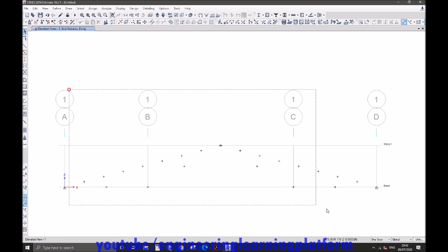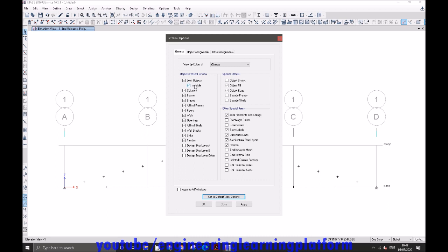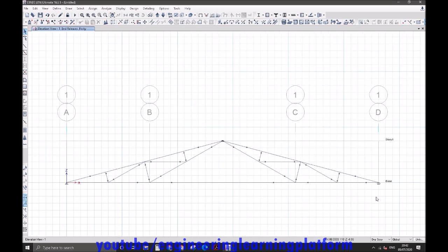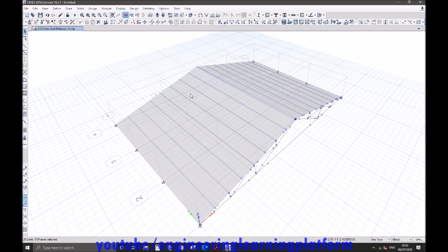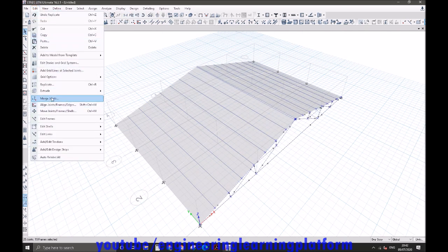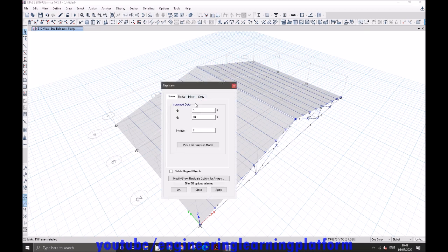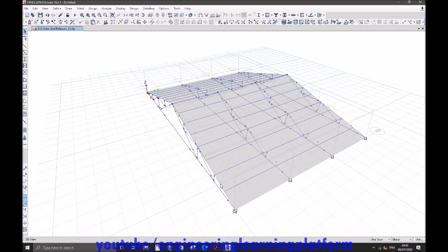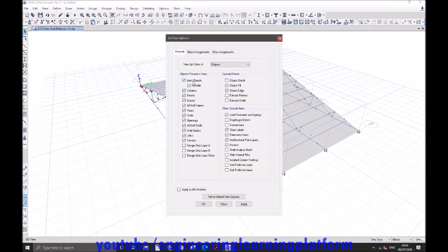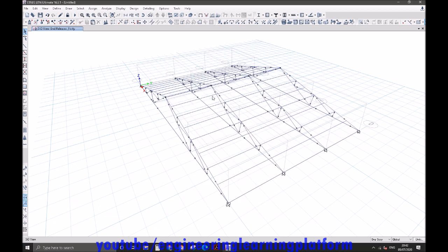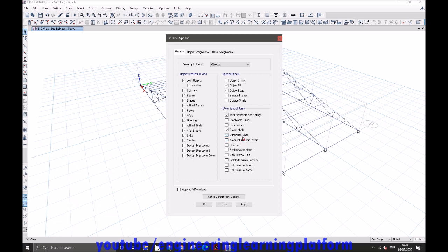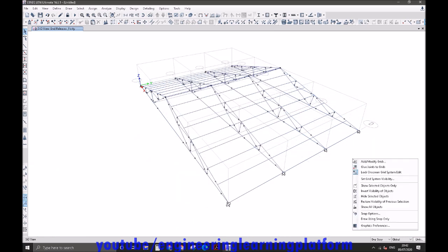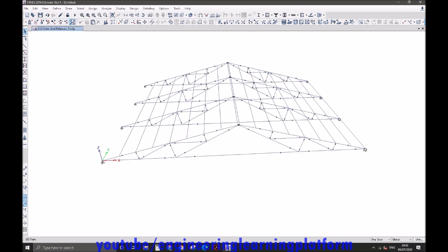Now we'll try to delete the extra joints which were used for modeling. Okay, so there are no extra joints as these points depict the location of the purlins. I'm gonna replicate it again to the other points. It's gonna be 3. Okay. So now the modeling initially is completed, I'd say. But basically, the purlins are connecting the truss members which are carrying the axial forces.